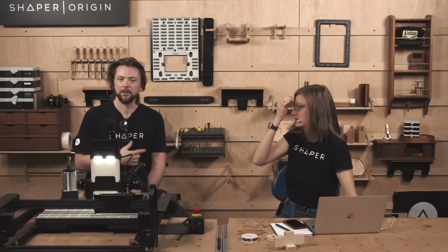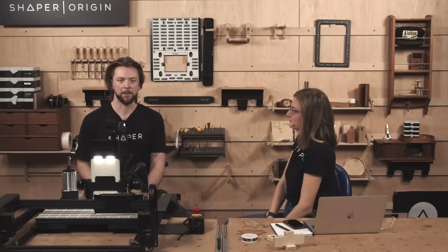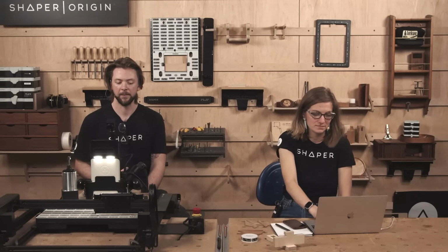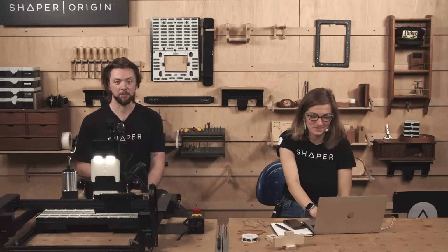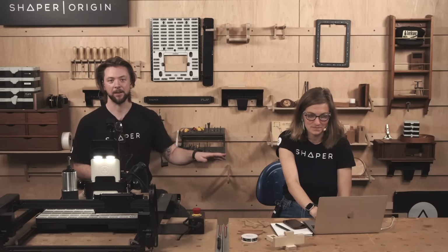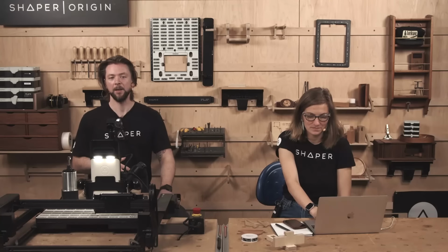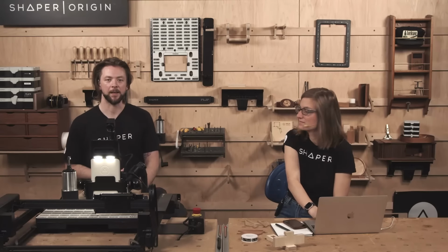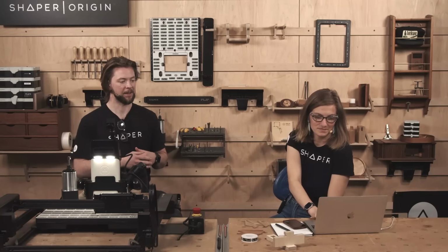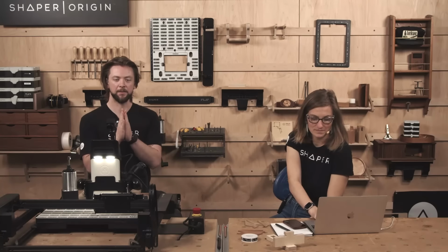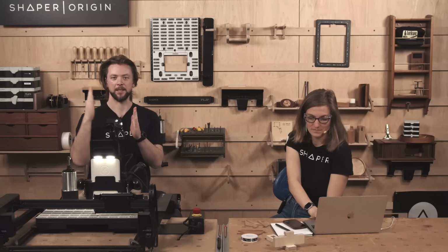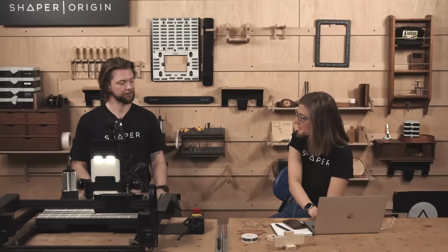As I was saying earlier, you can totally use Bench Pilot to pocket stuff. In fact, I might even just leave the 1/8" bit in there to pocket the entire thing, because again, I can do something else on the side while it's pocketing. The general rule with Bench Pilot and pocketing is it does a 50% step over. So whatever the diameter of the bit is, 50% of that is how much it steps over as it pockets this shape.